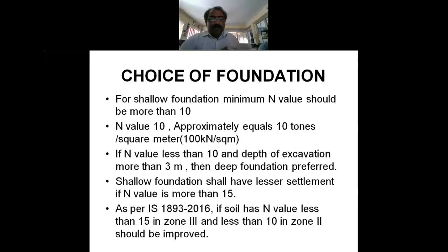Shallow foundation has lesser settlement. If you are applying a force on the soil mass, definitely the soil mass will sink and it will settle. If the N values are more than 15, the settlement will be very less.